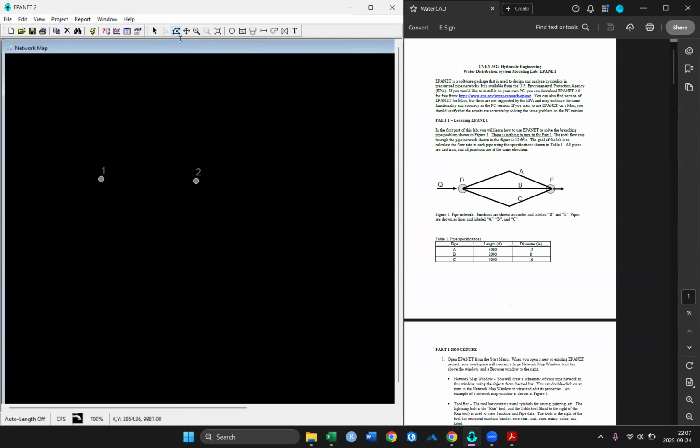All right, now I'm going to create some links. And this is the link tool right here, actually. Add a pipe. Click on that. And then just want to be in the ballpark, kind of over that. And if you click it correctly, it's going to give you that little white box there.